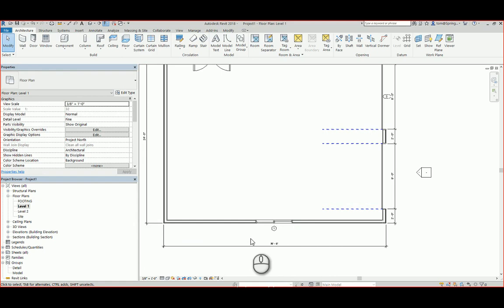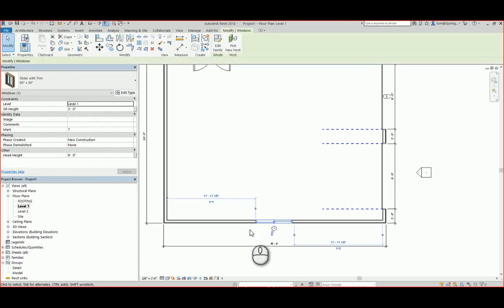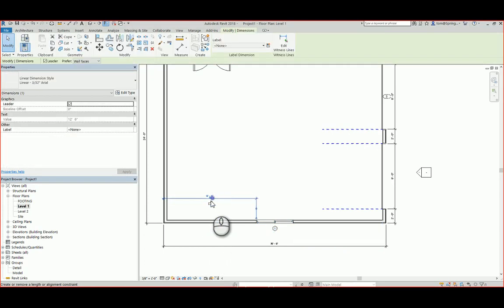But anyway, let's go ahead and put it there, and then when I click here, let's see what I've got left. I want to get a dimension from the outside there, and it should be 12'6" on each side, so I'm just going to go from this point and go 12.5. That gives me 12.5 feet like that. And I'm just going to go ahead and place that, and it's going to place it right there. And once I've got that, we are good to go. I'm going to take it and pull it down here, and do that.